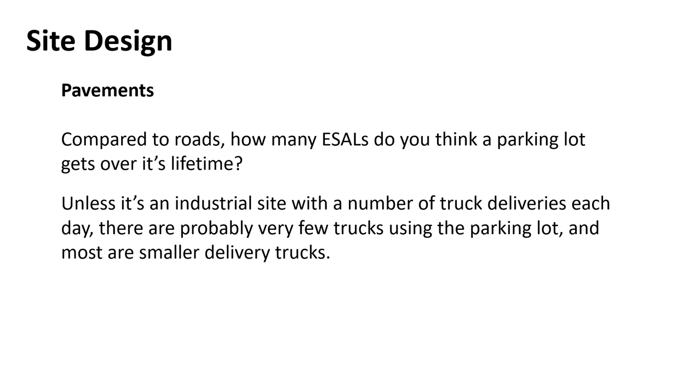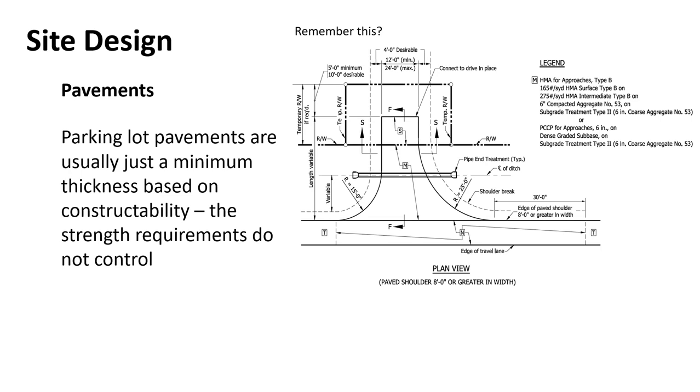So not all of that pavement needs to be beefy. If it's just general light vehicles, it's not beefy at all. Right? So just keep that in mind. Just think about what your use is, but generally most of these site developments, you're not going to get much truck traffic, or if you do, it's only in certain spots.